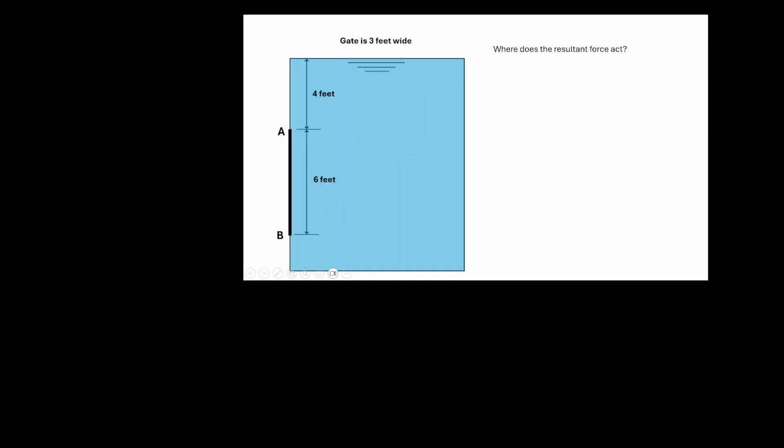There are times when you're going to have to know where does the resultant force act. And the simple answer to that is that it's going to act at the center of pressure. This is the equation that you use for the center of pressure. It looks like a lot, but it's really not that bad. That first term is the moment of inertia about the center of gravity, and then you divide that by the depth to the center of gravity times the area, and then you just add it to the center of gravity.